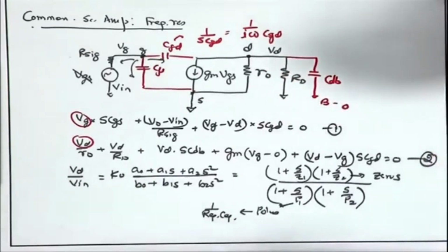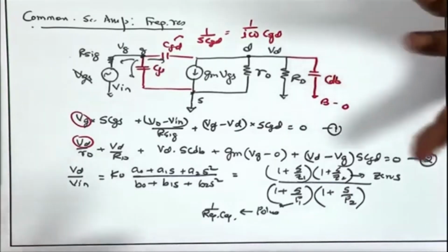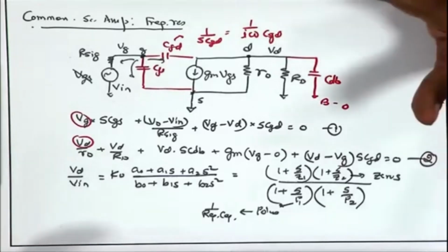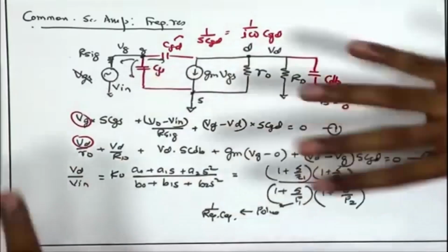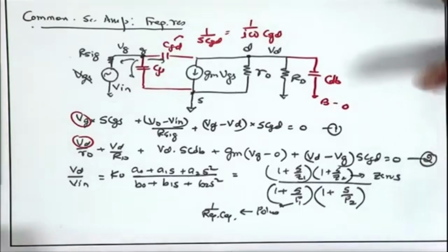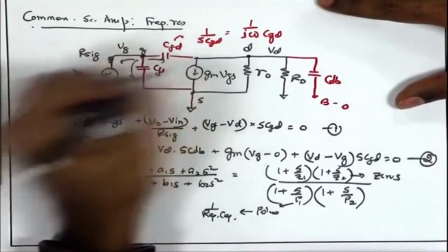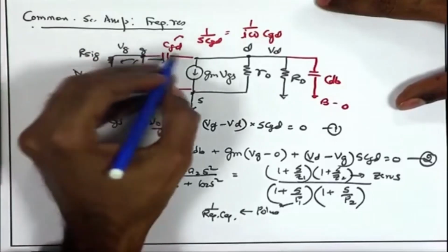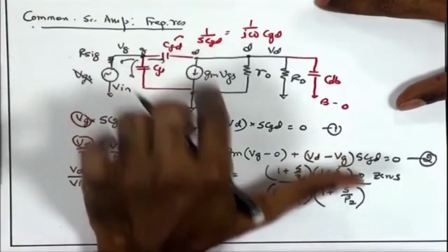But for hand calculation, for doing quick analysis, we use some tricks, we use some approximations which can give us approximately good results, fairly reasonably correct results, so that we can get started with the design. So, rather than going through this more complicated step, we go for an approximation. So, one of the key steps involved in that approximation, and most of you might be aware of that, is dealing with the Miller effect. So, all we need to do is get rid of the capacitances connecting two different nodes and reduce them to capacitances connected between those nodes and AC ground.